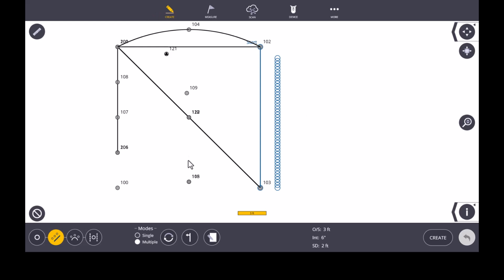The second option we have to look at the bottom is our button with a line and an arrow. If we click this button, it will flip the points from one side of the line to the other side of the line, while maintaining the same starting point so that start distance does not get changed. If I click it one more time, it will actually put points on both sides of the line. Let's get it over to our right, and we'll hit Create.